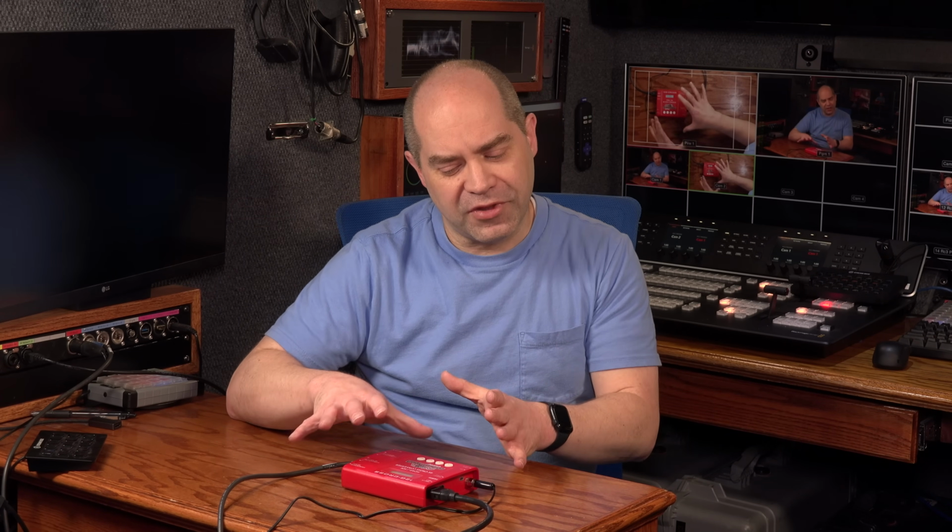But really the bottom line here is that having an external converter box that's doing that final conversion before it goes into your switcher is going to give you a much higher quality signal than you're going to get with the ATEM native converters. And so it's a good thing to keep these things in your arsenal of equipment, your tool bag, whatever, and allow you to do a better job of doing that final conversion, since it has to be done anyway. And so I very highly recommend keeping at least a couple of these things around. Okay, so there it is.